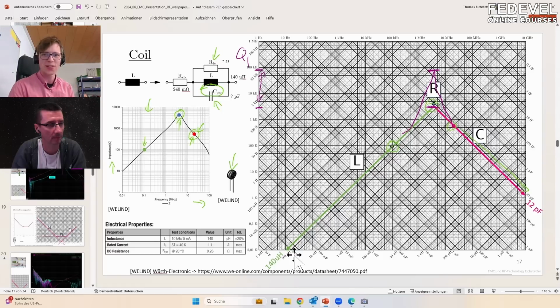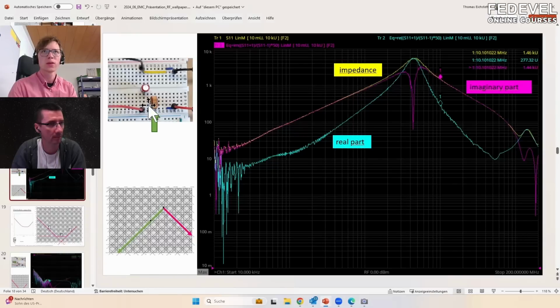So when you add 2 centimeters there, it doesn't matter. This would be an additional 20 nanohenry. So here it doesn't matter where you connect it, directly on the end or here in the middle. It's the same. Okay, I understand.